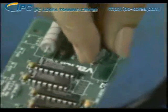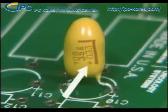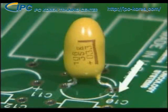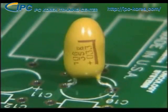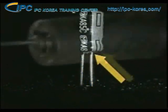Polarized capacitors also come with either axial or radial leads. The positive lead, or anode, will usually be indicated by a plus sign. This same plus sign is usually on the circuit board. There may be other types of markings to identify polarity on the capacitor.